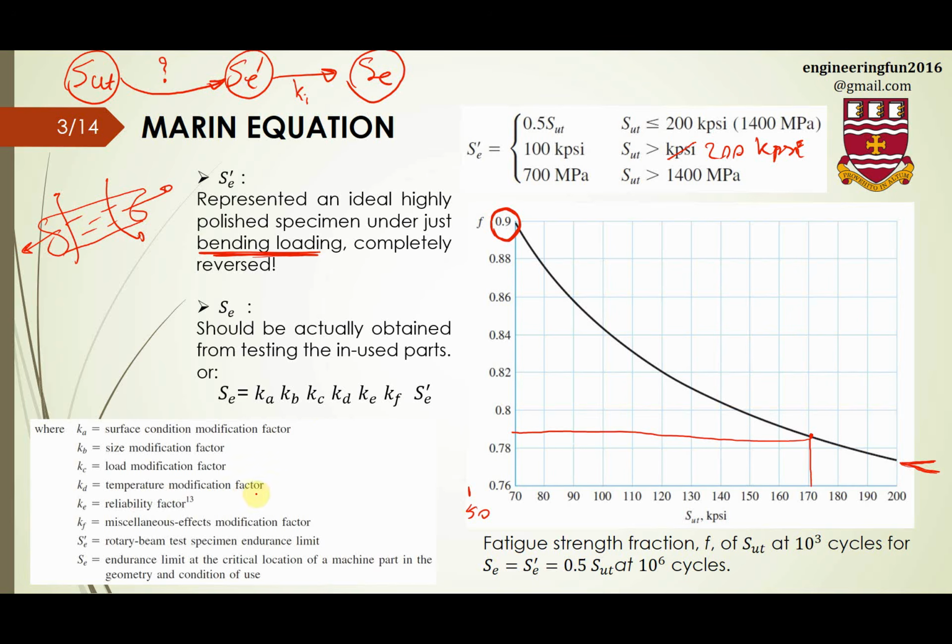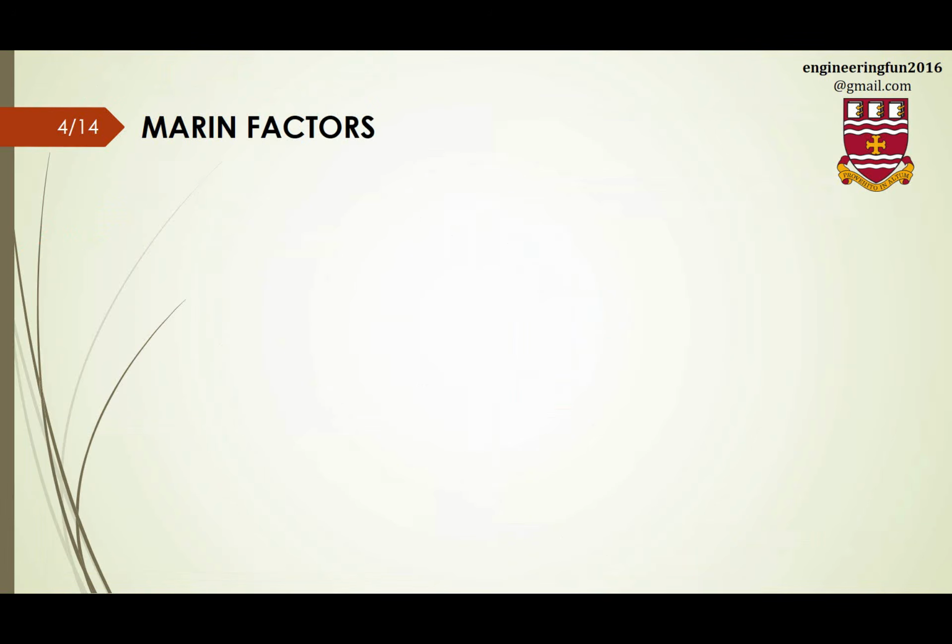Temperature modification factor, which is Kd. This is applied for very, very high temperature, or sometimes for very, very low temperature. Then the reliability factor and the miscellaneous effect modification factor. Usually that's one, we're not that worried about that one. Now I'm going to review all these factors in detail, one by one.